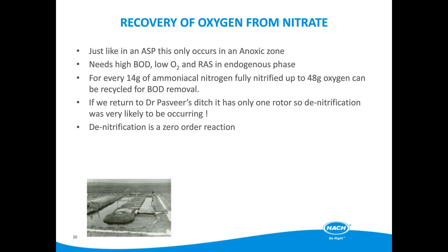the ditch. But that 14 milligrams per litre of nitrate contains the equivalent of 48 milligrams per litre of oxygen, and that is available for BOD removal. And this is a dissolved oxygen concentration that could never be achieved using air in an aqueous solution. If ANOXIC zones can be formed within the ditch, then this combined oxygen can be utilized for BOD removal by the heterotrophic bacteria within the biomass and hence saving energy.